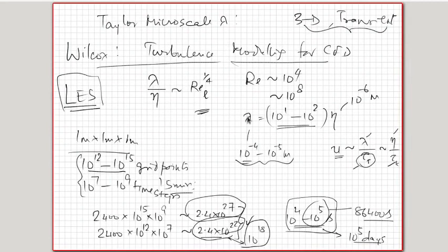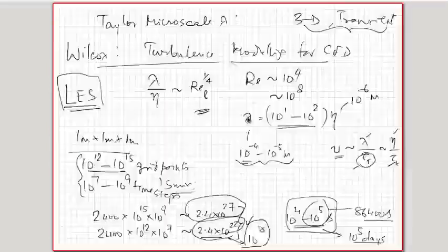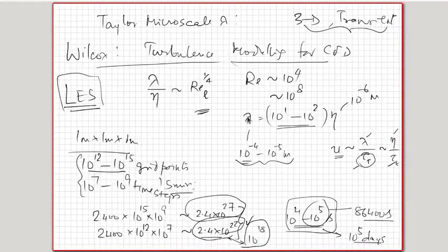But what we need is the net effect of the turbulent fluctuations and the averaged values of shear stress and heat transfer. And more often than not, they are steady state systems. That is, the mean flow is steady. The fluctuations may be transient, but you don't need to worry too much about them. In which case, then we go into modeling of turbulence.